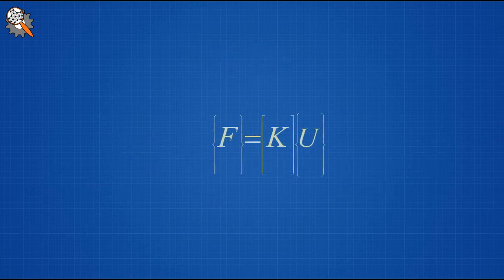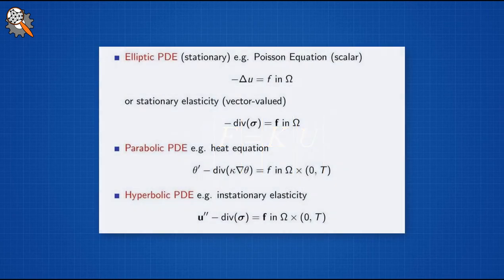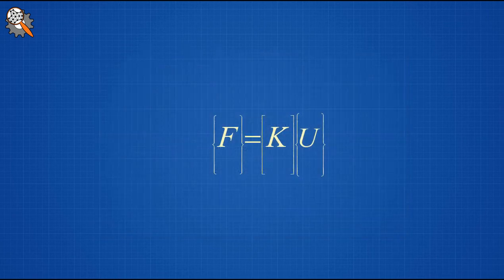Solving a physical problem by finite elements transforms the analytically difficult, if not often impossible to solve, partial differential equation into a set of algebraic equations simple to solve. The size of the final algebraic system, which means the number of equations to be solved, is defined by the total number of degrees of freedom of the system, meaning Nt.